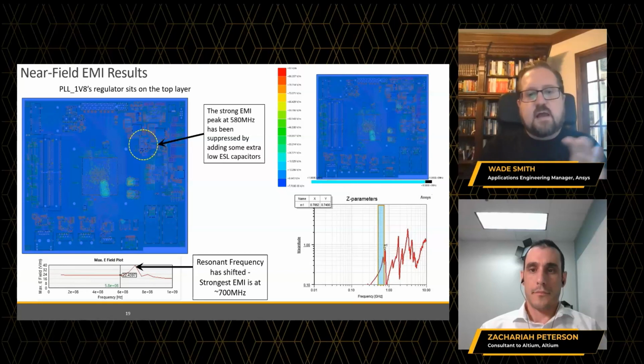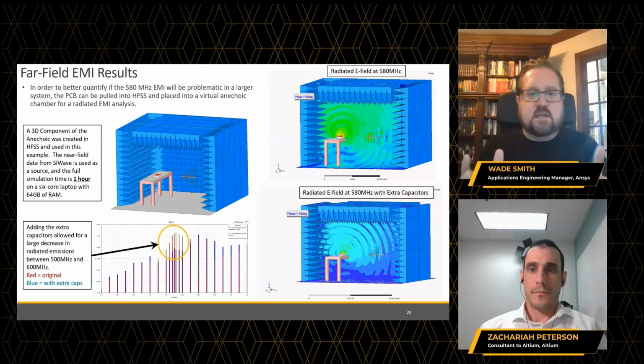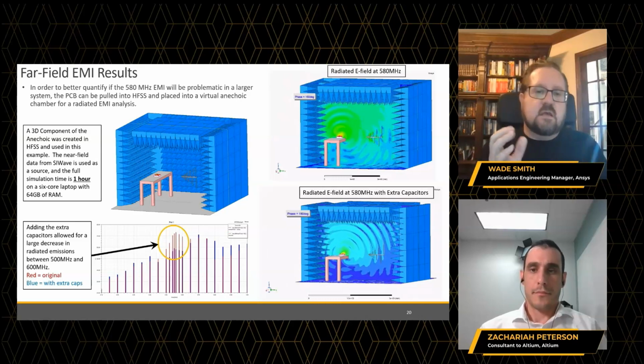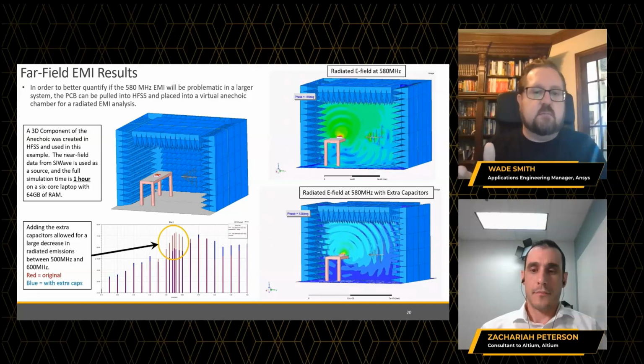And to do a final check of this to make sure it works, we're going to use HFSS and pull in an actual 3D component for an entire anechoic chamber. And we're going to use this near field information that SiWave gave us and be able to simulate this whole thing in a 1 meter chamber.